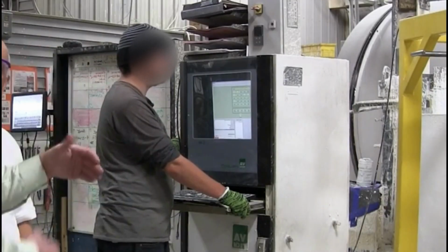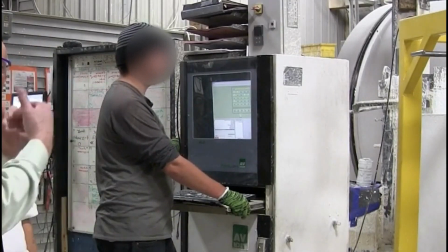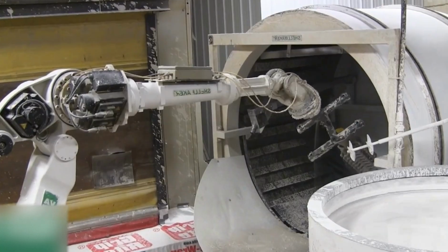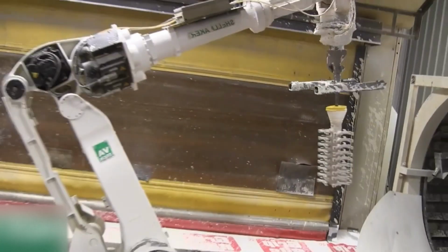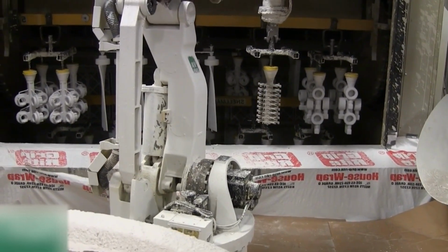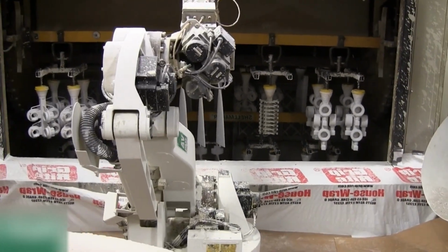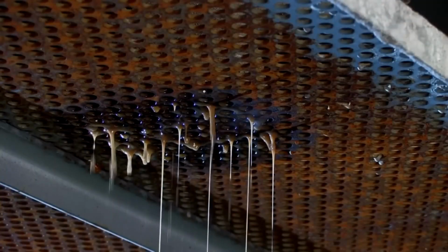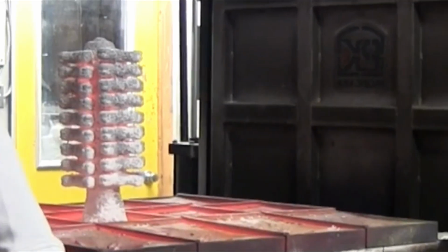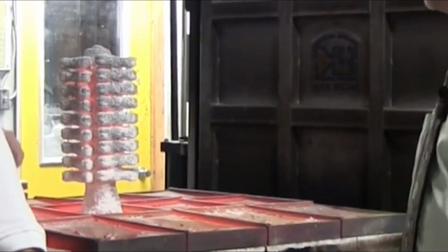The dipping and sanding of the casting tree are fully automated and process controlled to ensure the shell thickness withstands the casting pressure. The shell is kept to dry, where it may be subject to a stream of air. Once the ceramic shell has dried and hardened, it's heated in a furnace to melt out the wax, hence the name lost wax process, leaving behind a hollow ceramic mold.